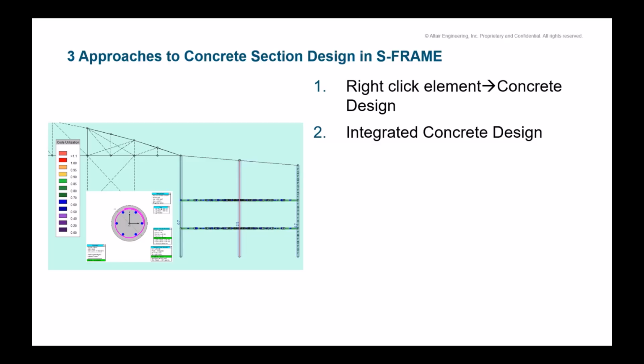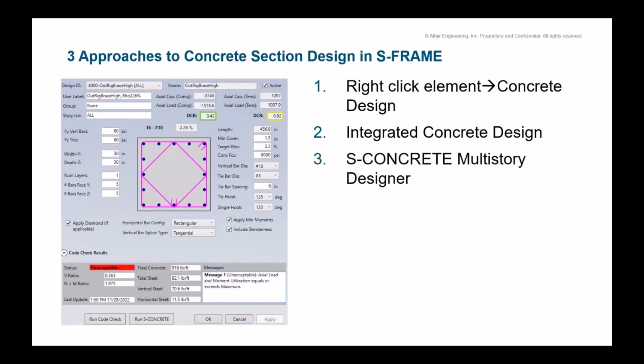And the last one, and the one that we are going to talk about today, is the S-concrete Multistory Designer. This tool allows you to import the analysis data from your model, not only S-frame but also ETABS, specify the reinforcement, and execute all of the different design checks that are needed, as well as obtain the report results.